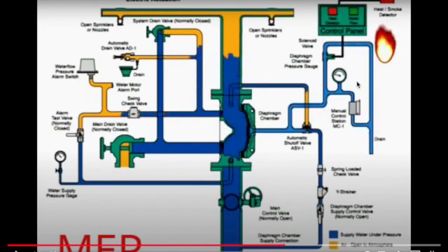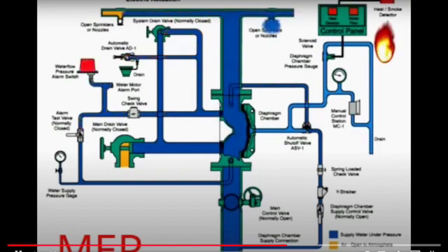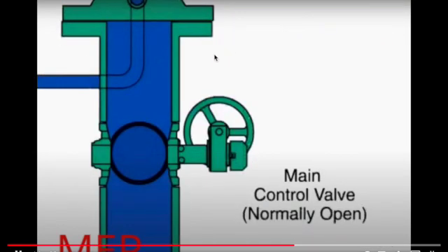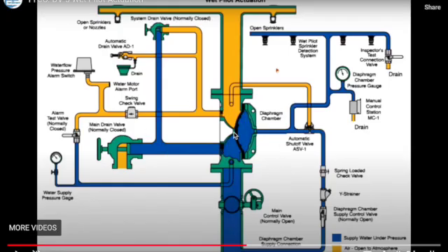So here you can see, once the system becomes depressurized, the diaphragm opens and the water is distributed throughout the system. So it's another type of the same water spray system. In this, instead of using fire detectors, we usually use a wet pilot sprinkler detection system, in which we use a sprinkler system instead of detectors and solenoid valve.